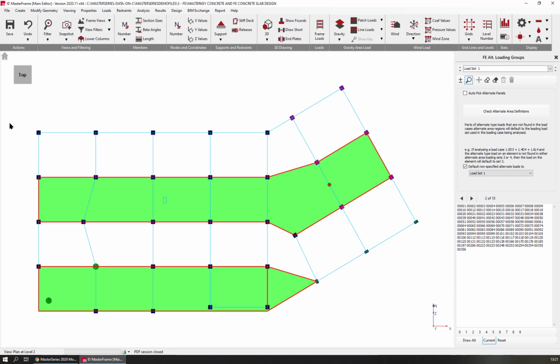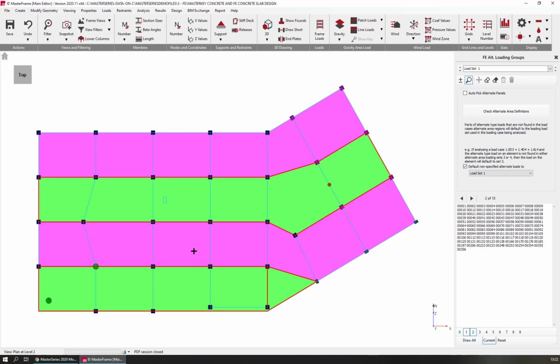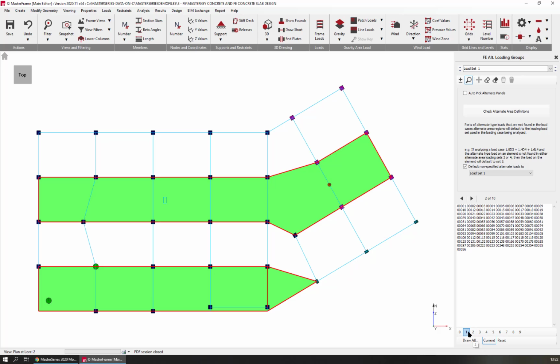So very quickly, pattern 1 is here. So that means that anything that's inside those slabs, if I turn on my load values D1 and L1, it will then activate them. And to complement that, I then have its brother, pattern 2, that complements that. So that allows me to go max, min, and obviously min, max, and get the patterns I want. But that's only in one direction.